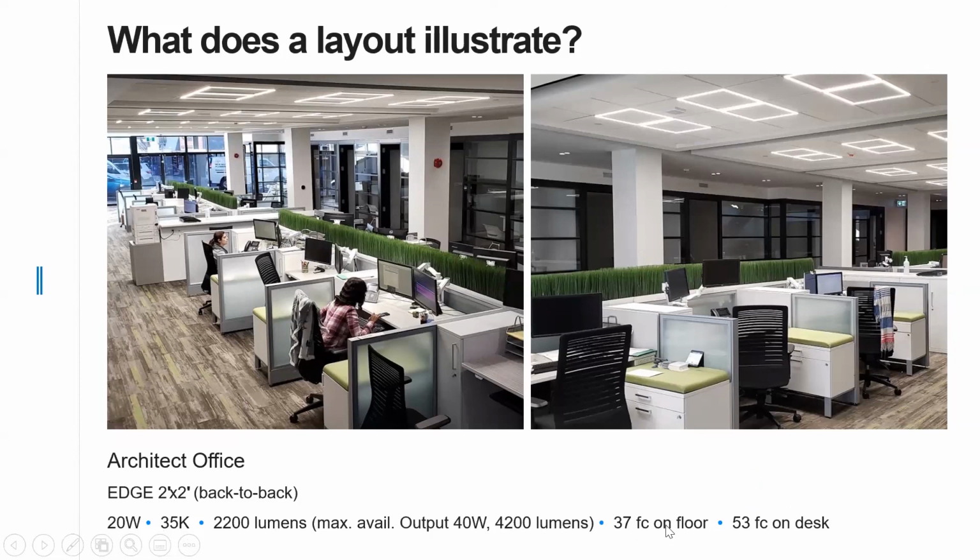So we delivered 37 foot candles on the floor, which was tremendous, and 53 foot candles on the desk. And that's probably a little higher than many offices, but they were doing some color matching, and they wanted higher light levels with excellent CRI, and chose the edge for those reasons. They can always reconfigure that and go even higher.